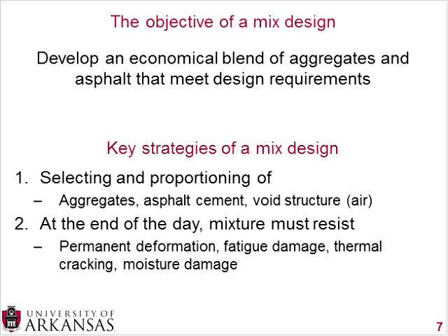Some basic key strategies of a mix design, and as you go through the examples of the 3 different mix designs, we'll see more focused areas of this. You want to select and proportion the amount of aggregates, the amount of asphalt cement, and the amount of air that you have in your mixtures. And at the end of the day, you want to prevent pavement deterioration or pavement distresses, such as permanent deformation, fatigue damage, thermal cracking, and moisture damage. So again, these objectives and these strategies are for all types of mix designs.